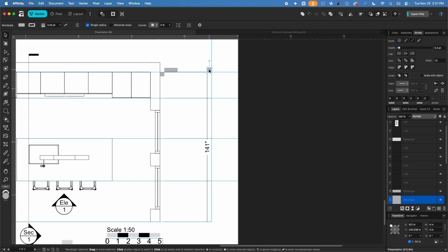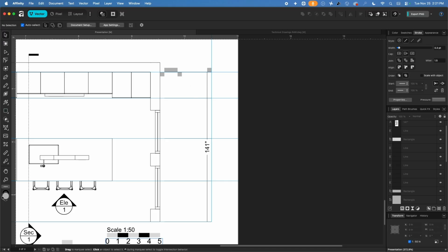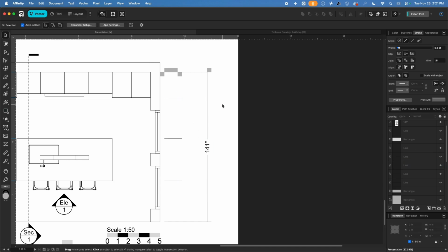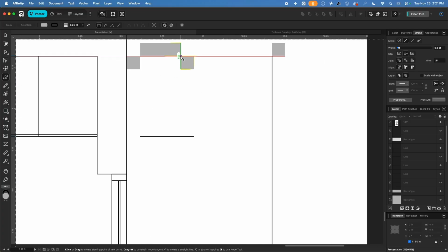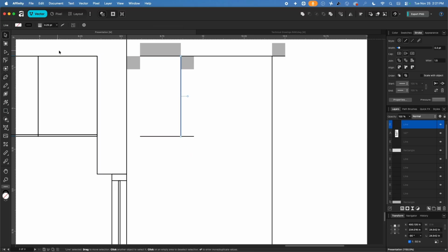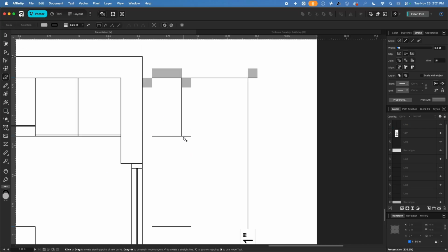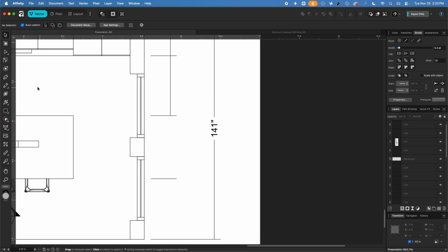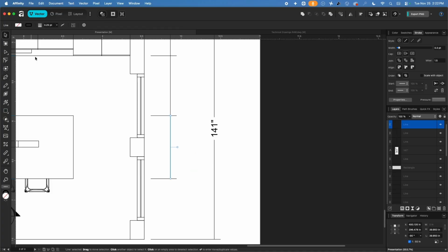This line here, I make a copy and paste, bring this to there because now these shorter lines can be shorter to this dimension. Okay. And I will now from here straight down holding Shift, draw a line. Click somewhere else. Pen again. From there, hold Shift onto that line. Click somewhere else. Snap, hold Shift, snap, click somewhere else.